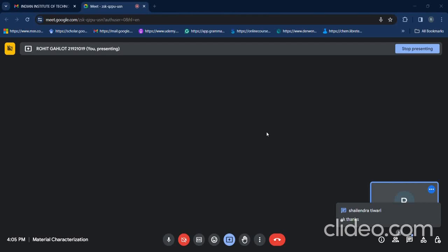SE2 is when your primary electron undergoes scattering with your sample and manages to escape somehow, however significant energy is lost due to the scattering. And SE3 is when your BSE electron hits the specimen chamber and additional electrons come out. Therefore SE1 is the most important, and generally this is used in topographical analysis.